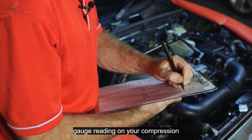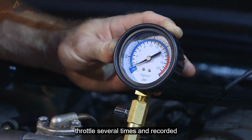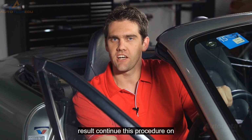Record the gauge reading on your compression analysis chart. Briefly blip the throttle several times and record the highest reading. This will ensure an accurate result. Continue this procedure on all remaining cylinders.